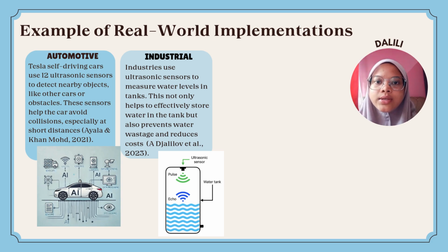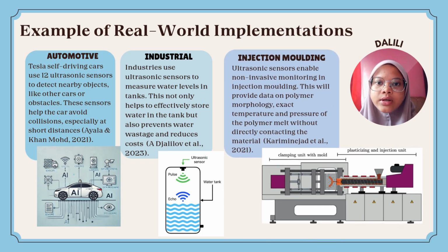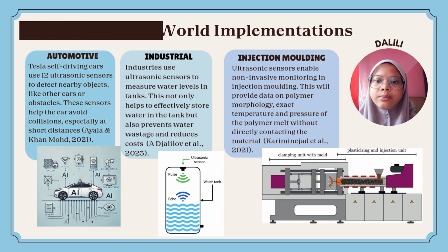The last one is injection molding. Ultrasonic sensors enable non-invasive monitoring in injection molding. This will provide data on polymer morphology, exact temperature and pressure of the polymer melt without directly contacting the material.